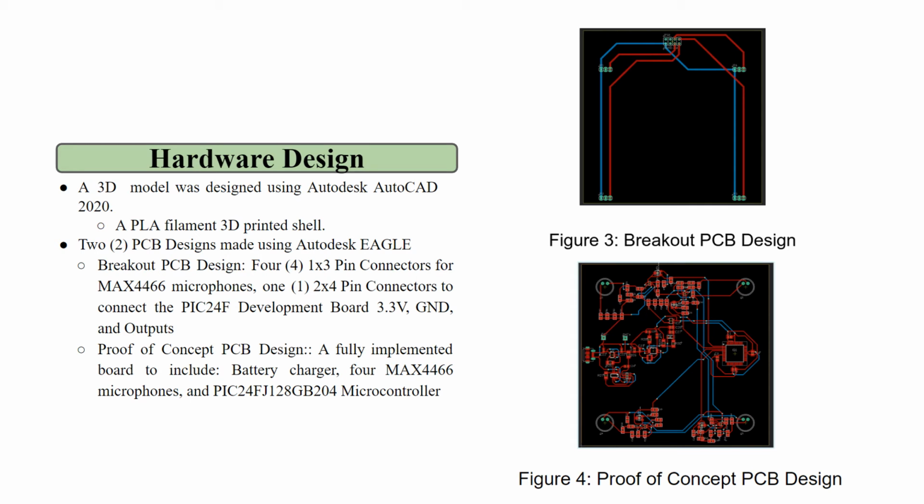Finally, a proof of concept board was designed with the idea of how this project would be marketed if we were to fabricate it. It would include not only a fully implemented battery charger, but also 4 of the MAX 4466 microphones already built into the board itself, and a PIC24FJ128GB204 microcontroller from Microchip.